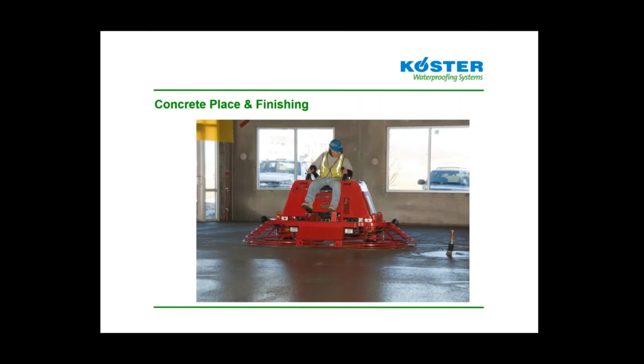Concrete floor slabs ideally should be finished with a minimum amount of pressure and consolidation for several reasons. Finishing equipment and procedures should be selected to meet the proper requirements for flatness and level without burnishing or really densifying the floor, for most interior floor slabs that are going to receive floor coverings or floor coatings. These dense, heavily troweled surfaces, first of all, slow the rate of drying significantly, and they inhibit the bonding of most underlayments, topically applied coatings, or any other components of the floor covering system.